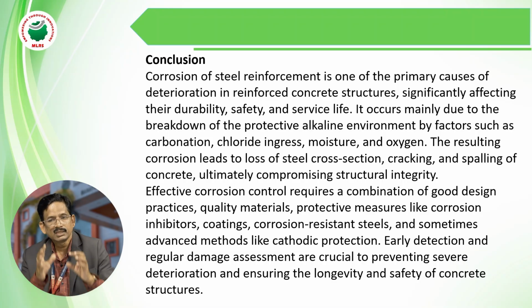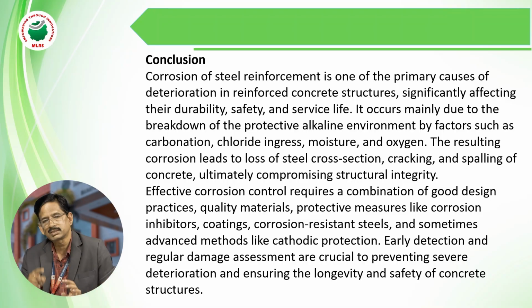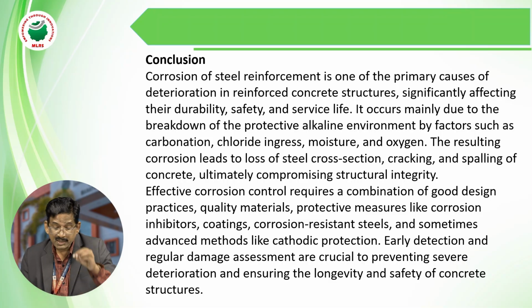In a similar way, for whatever structure we design or construct, the strength aspect and durability aspect are equally important. The corrosion of the steel reinforcement is the durability aspect. It is very, very important, along with safety and service life. It occurs mainly due to the breakdown of the alkaline environment. I told already, it is because of the environment.